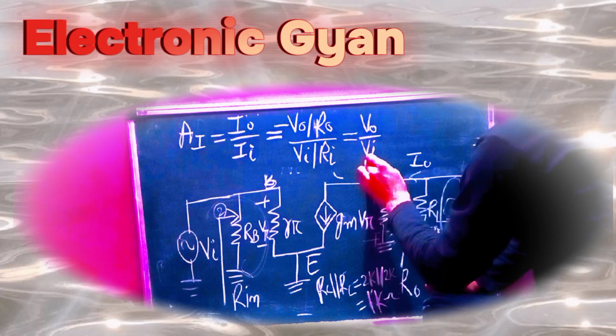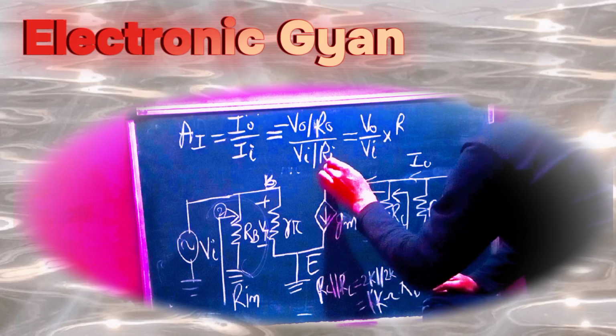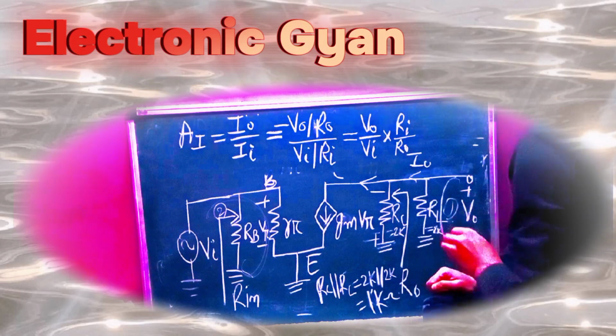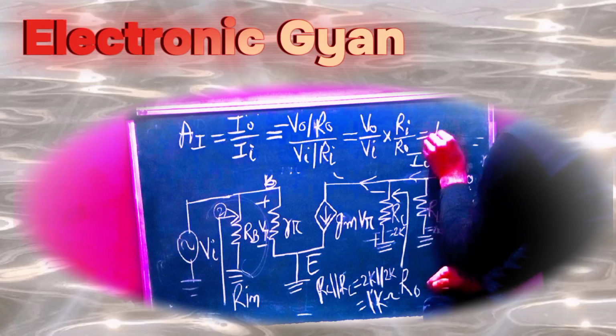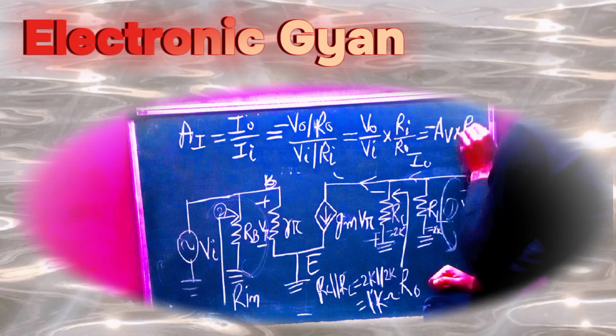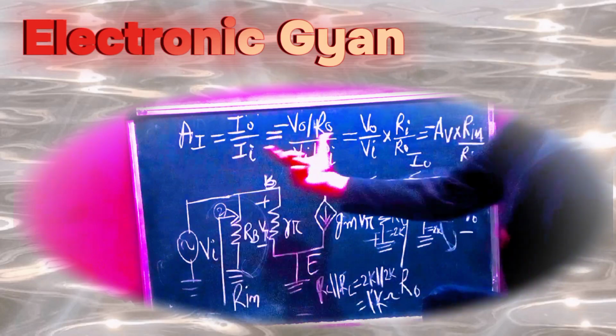And if you see voltage, V0 by Vi into, my Ri will go upside and R naught will come down. So this means current gain is minus voltage gain into input resistance upon output resistance. This is my current gain.